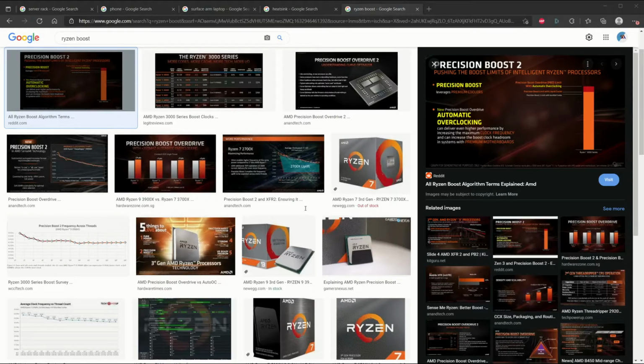One thing, obviously, that you want to keep in mind with your CPU is temperatures, how hot the thing is getting, and throttling, which is effectively, once it gets to a certain point, it kind of shuts down, so it lowers its performance at the throttling temperature. A good temperature for CPUs to be at is obviously under 100 degrees. These are measured in Celsius, but definitely under like 90. So sitting in that 70 to 80 range is a good range to sit at, generally when you're doing stuff, as to not get too hot. Heated CPUs for a long period of time obviously hurt the longevity of it.